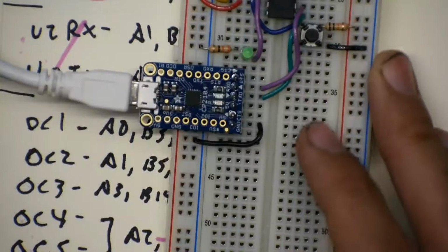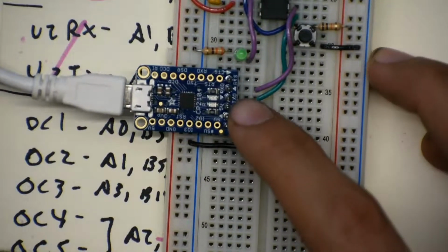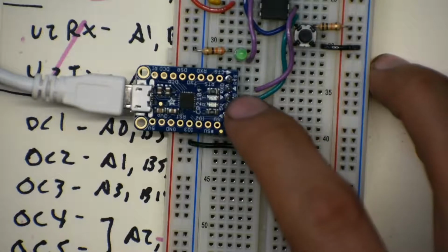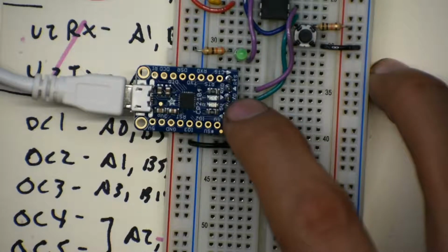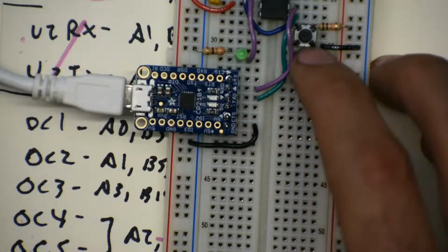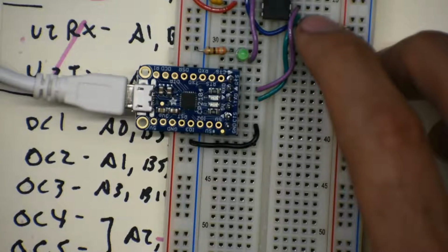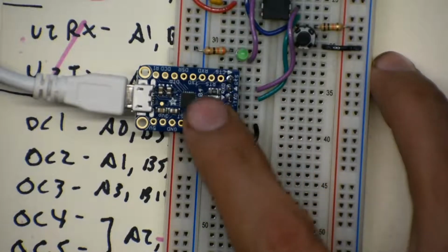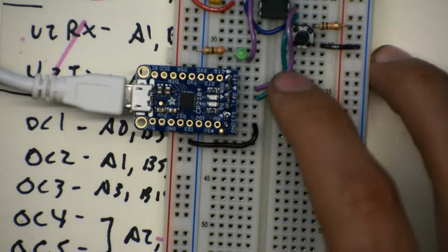Take a look at that. Okay, and they kind of show arrows. The TX pin has a little arrow pointing out, so the friend's TX pin is going to the PIC's RX, and then the PIC's TX is going to the friend's RX. So those are the only connections we need: the ground, the TX, and the RX.